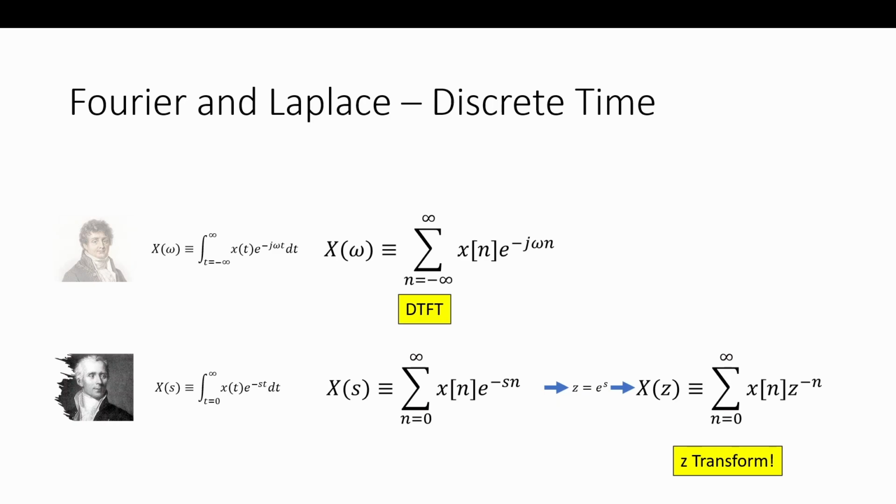Even though it's digital, doesn't mean we can't have any frequency that we sample in the time domain, right? So we want to know the frequency response for any frequency coming in that was sampled at the sampling rate. So that's the DTFT. You can do that by zero padding in an FFT, get the samples of the DTFT, but that's it. It's saying n is going from minus infinity to infinity, as opposed to the FFT where we restrict n to be 0 to n minus 1. I'll tie those together.